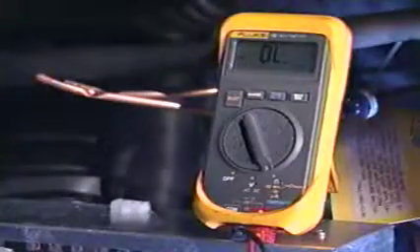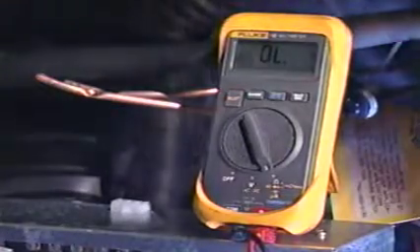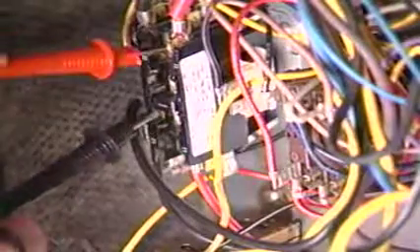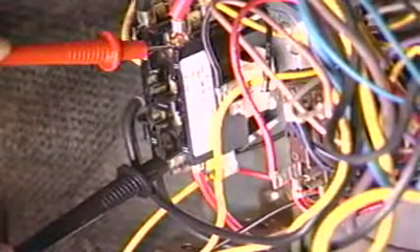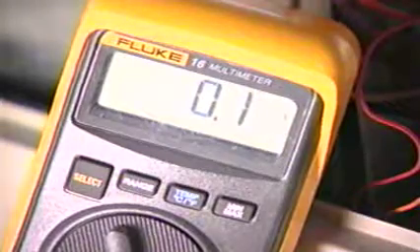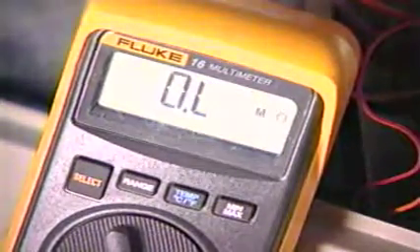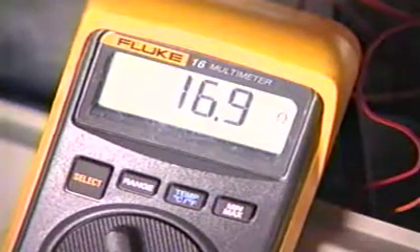If an ohm meter is used to check the contacts, there should be no current flowing through the contacts, but the coil should be energized. The wires should also be disconnected from the contactor contacts. When the contacts are in the closed position, the resistance reading through the set of contacts should be very close to 0 ohms. Always be sure to check all sets of contacts. A high resistance reading indicates that the contacts are no good.